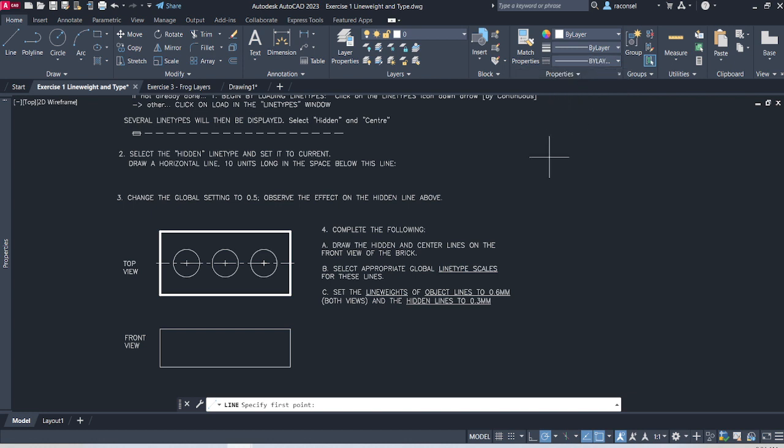What does that mean? Well, let's look over a little bit to the left, to the layers menu. If anybody's worked in Photoshop or Illustrator or anything like that, you'll be familiar with layers. AutoCAD also has layers. What layers allow you to do is assign a bunch of properties and group certain kinds of things together. So here, whenever you start up a drawing, you end up with basically two layers, layer 0 and def points. Ignore def points. That's just a thing that AutoCAD needs to do.